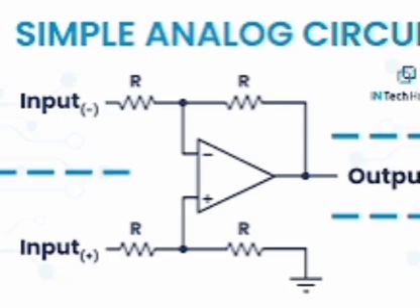Efficiency, ripple factor gamma equal to 0.48 for full wave rectifier, form factor F equal to 1.11 for full wave rectifier, crest factor C equal to root 2 for full wave rectifier. Eta equal to numerator part 8 into RL, denominator part pi square into RS by 2 plus RF plus RL. Eta is maximum when RS equal to RF equal to 0, ideal case, and eta max equal to 8 by pi square, that equals 81.2%.